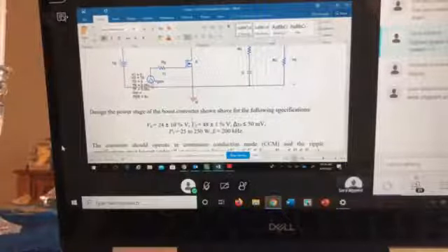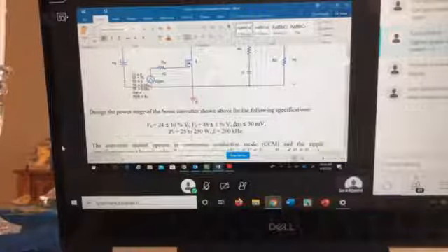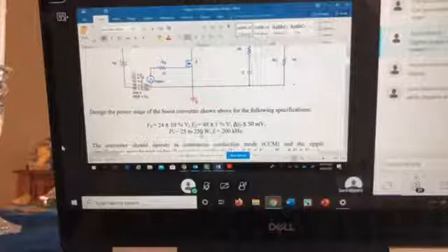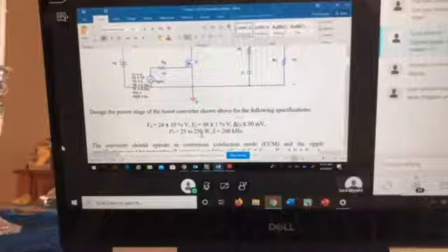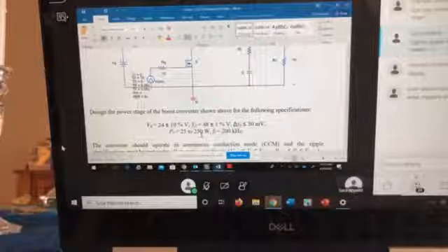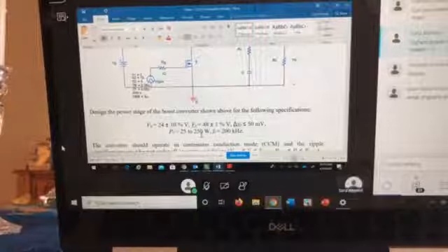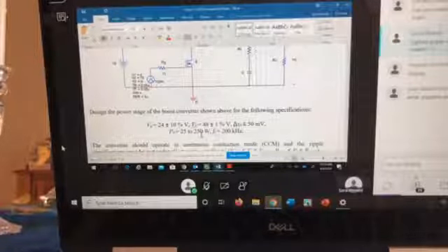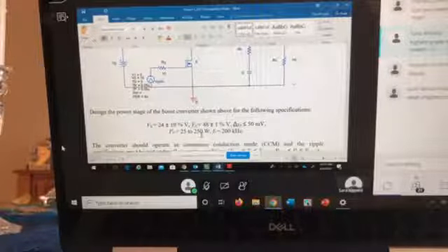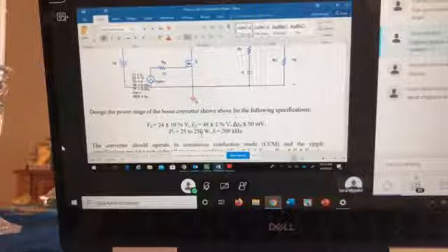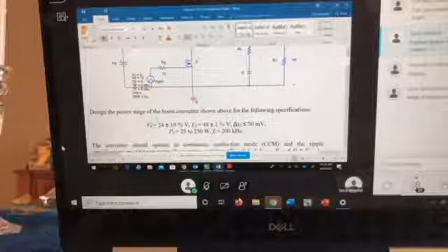I think this was a big confusion to a lot of you guys, but this is the range of operation. What are the things that you can change? You can change your input, right? Because you have a DC source that you can play with. Imagine this DC source is like a PV. One time my PV is giving me 12 volts, and one time my PV is giving me 5 volts, based on how much sun there is. So this will change. That's why we have an operation range for this VG.